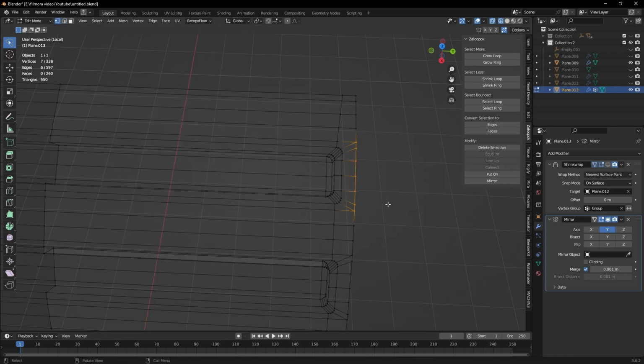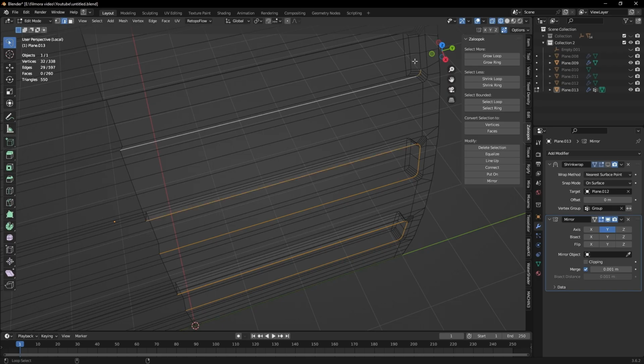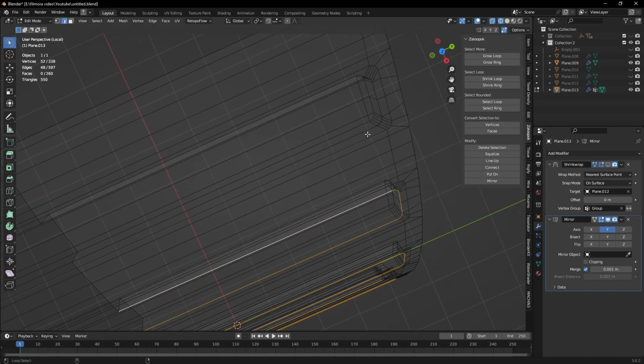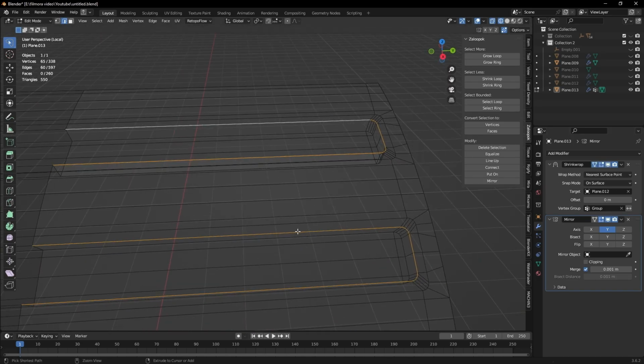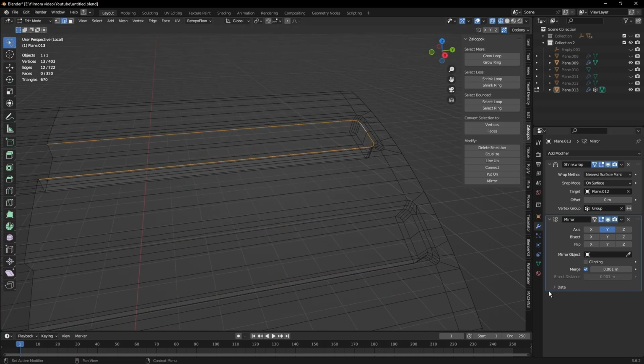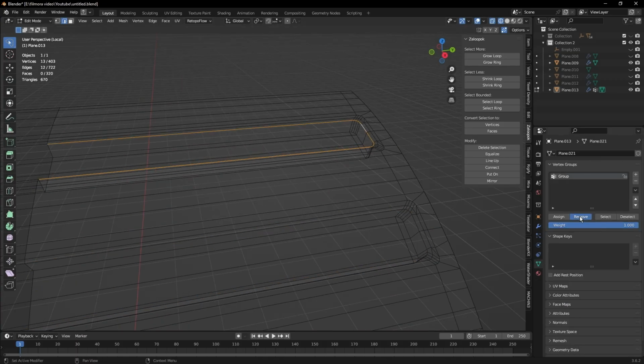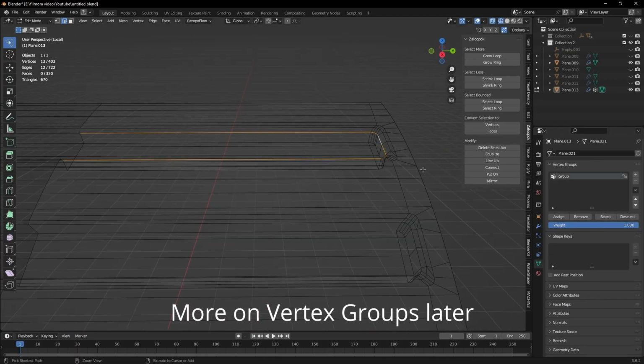Use Loop Tool's Space to even spacing. If the mesh has no modifiers, make a tessellated copy and shrink wrap the detailed mesh onto it to preserve curvature. If you don't want modifiers to affect everything, plan to limit them with vertex groups.